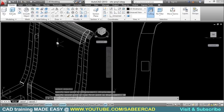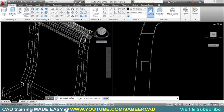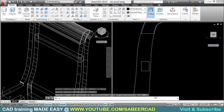Next, I'll extrude this profile. So I'll click on extrude. I'll select the profile and the height of extrusion is 34.5. This value appears as a default value. So just give an enter.